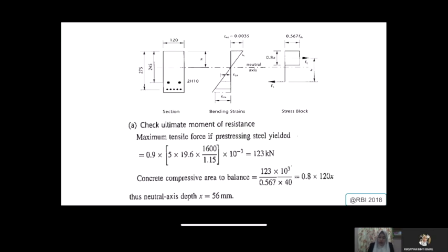we have the strain, SB, and here they draw the upper reinforcement as well. The same thing: the concrete maximum strain is 0.0035 considered here, the stress is 0.567 fcu, and the height of the block is 0.8x. Here is where you consider the D. This is your D for A, and D for B, and this is the D of A, the position of the reinforcement that you want to provide.